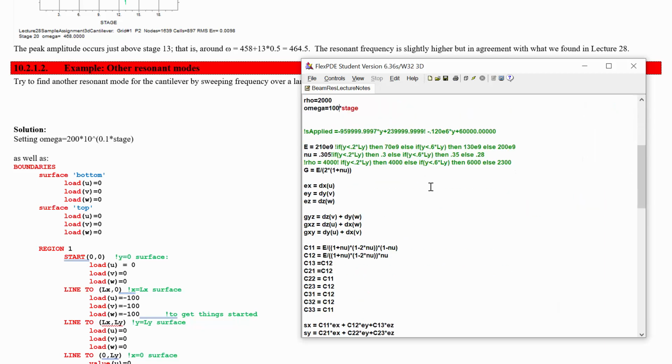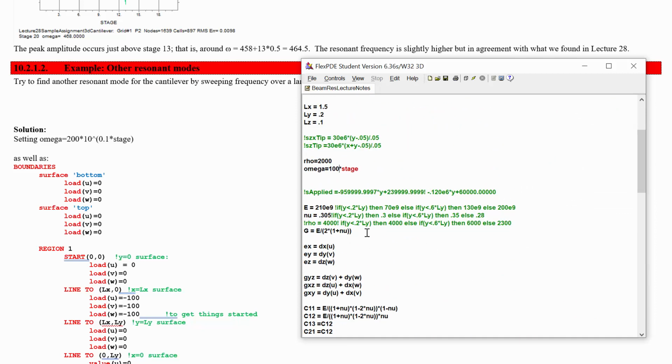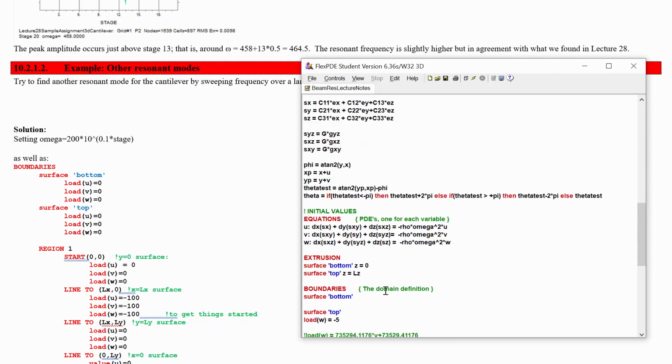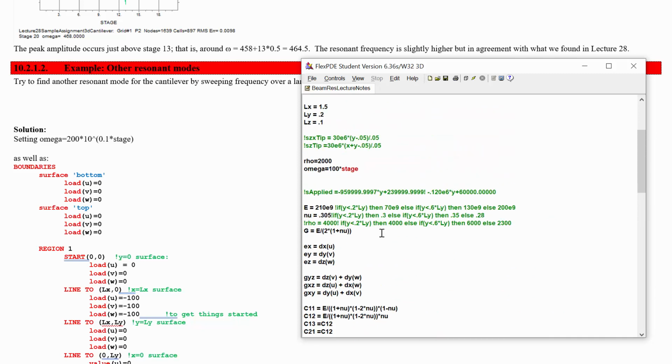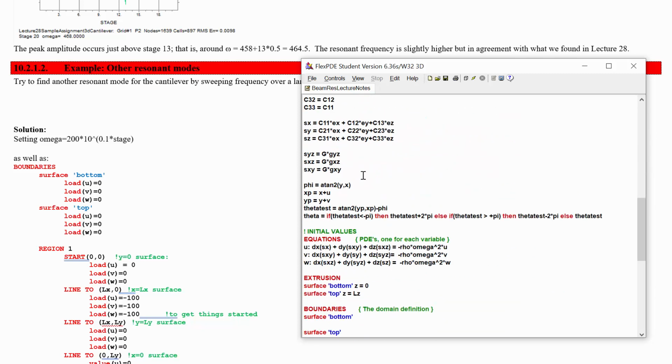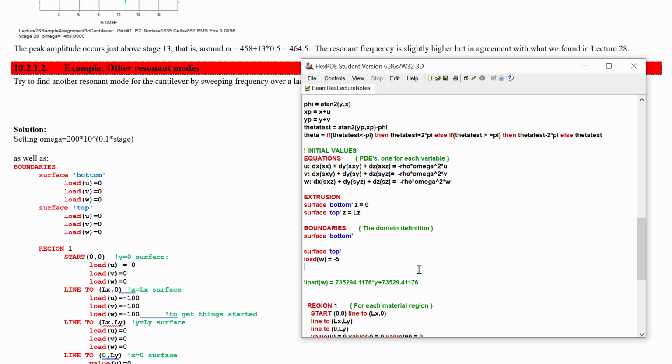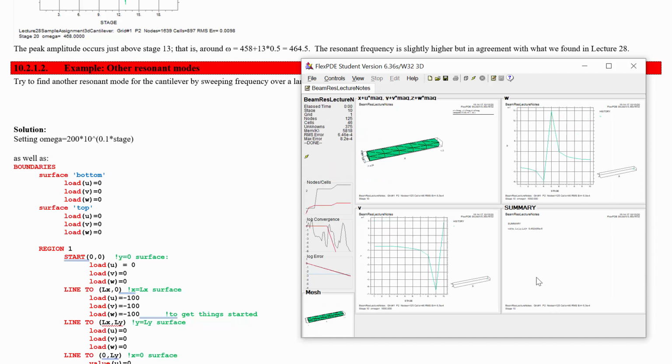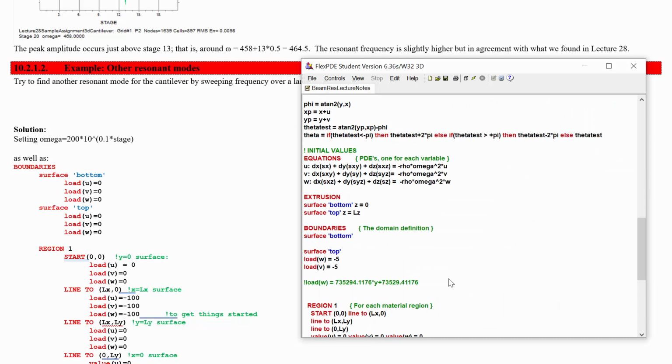The difficulty is we're not actually giving it an excitation in Y except through the Poisson's ratio. So we'd have a better amount of success if we just put some small stress on it. Load V is equal to -5 as well, say. Now we can get, wow, that ran very fast. I don't know why that ran so fast. So this is showing us a much larger amount of displacement happening in Y somewhere between 9 and 10.